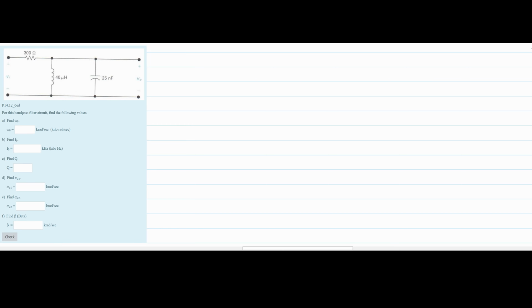Now, this is heavily formula based, and these formulas can be found in the notes linked below the like button on about page 119. And so it's important to first build the actual voltage divider for this. That's super important because it's just important to understand it. To build the voltage divider, we would need to combine these two impedances together. We will call it R0, and we know that there's some voltage across this. And then we would say that H of s is equal to V0 over V input.